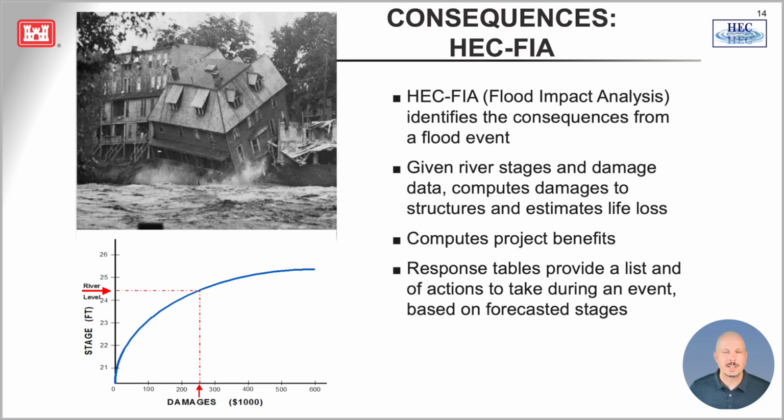Finally, the flood impact analysis HEC-FIA software is used in SWMS to identify consequences from a flood event. HEC-FIA models contain structural and agricultural inventories with stage damage cost relationships data. With the additional input of forecast stage data from HEC-RAS, HEC-FIA estimates the potential threat to life and damage costs for structures in agricultural areas. HEC-FIA also provides impact response actions for water managers to plan for during a real-time event.